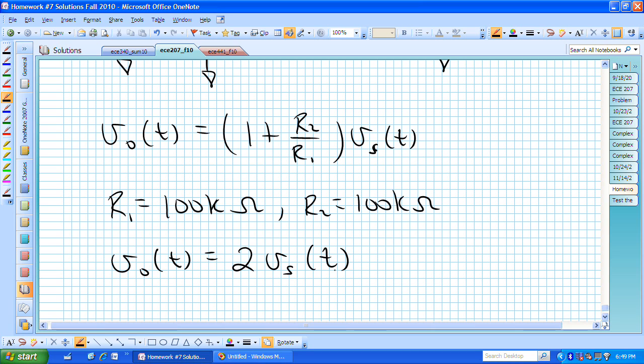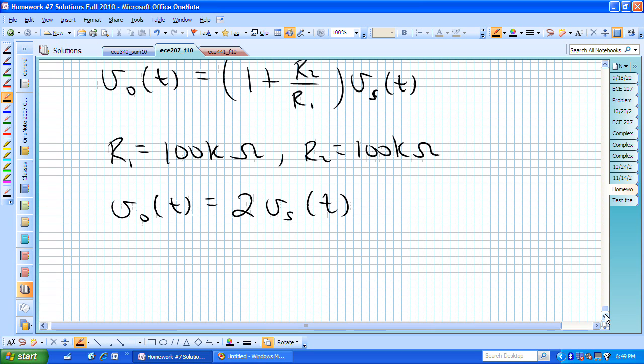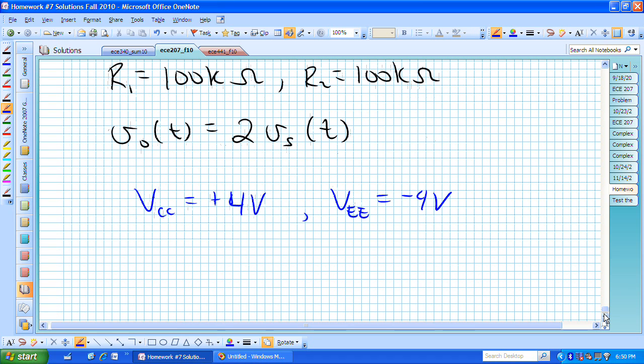What this particular exercise tells us is that our supply voltage is actually limited to, let's say, we'll call the positive voltage 4 volts, and the negative voltage as well, and these are what we're plugging this op-amp into. That's what's supplying our power to activate this circuit. We also are told that the output maximum current is limited, and they always are in an op-amp, but this one is I sub 0 max.